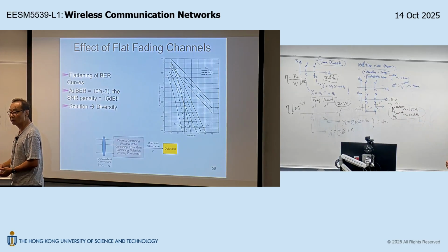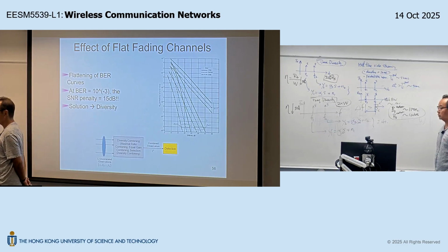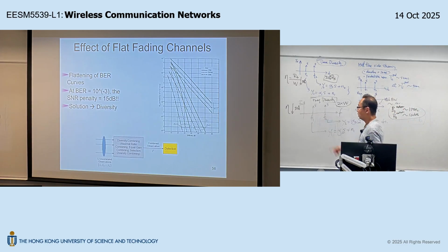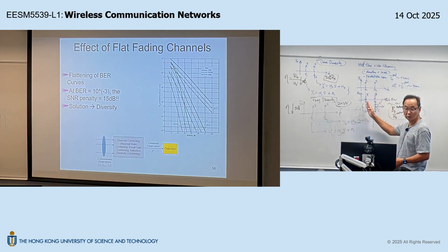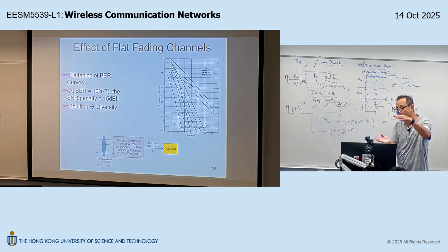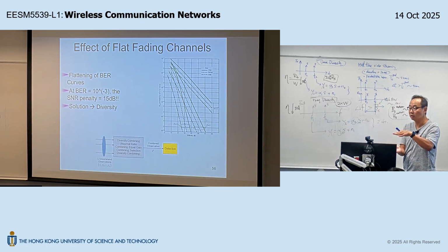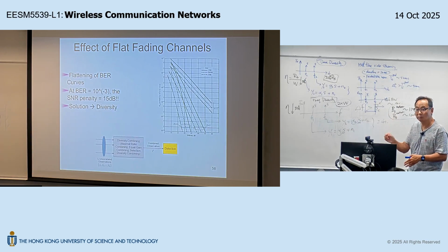How about frequency diversity? Can I rely on frequency diversity for this? Of course, yes, right? Because for frequency diversity, I'm going to send the same symbol twice simultaneously on 2 different channels. So these 2 transmissions happen at the same time, but on different frequencies. So if you look at the timing diagram, at T1, the receiver will be able to capture both observations from 2 different frequency channels simultaneously. Is that okay? So the latency can be arbitrarily small.